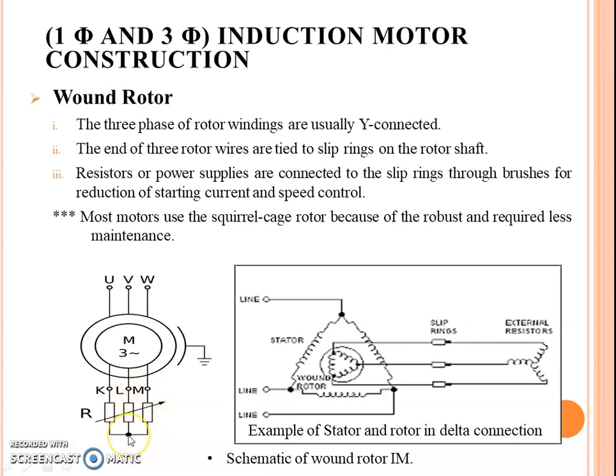So a resistor or power supply is connected to the internal Y connected rotor through the slip rings and brushes for reduction of starting current. The main purpose of this construction is to limit the starting current.